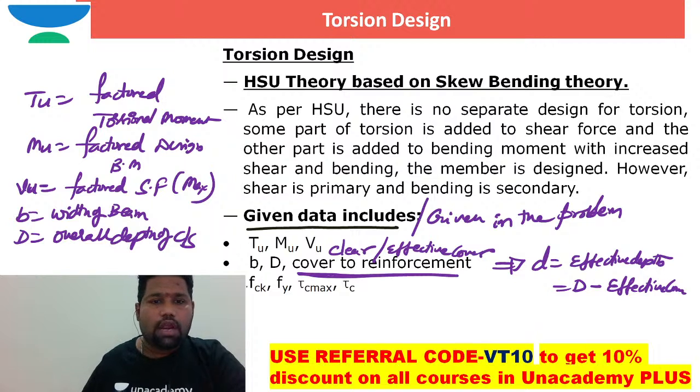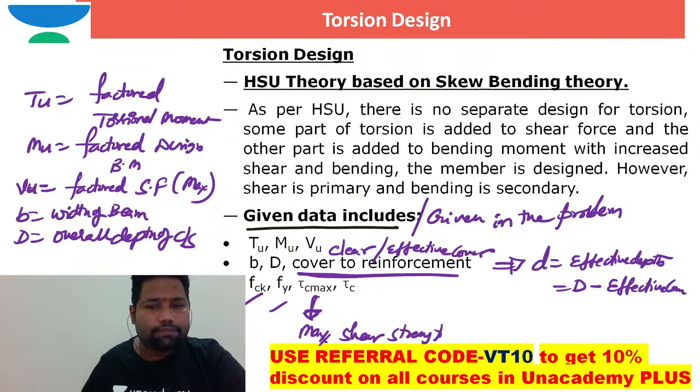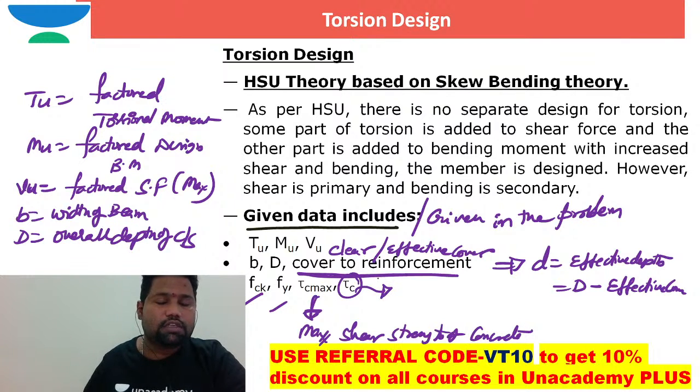And they will give you fck, the grade of concrete. They will give you fy, the grade of steel. They will give you tau c max, maximum shear strength of concrete, or limiting shear strength of concrete indirectly. What is tau c? That is the shear strength of RCC beam with percentage of tension steel.